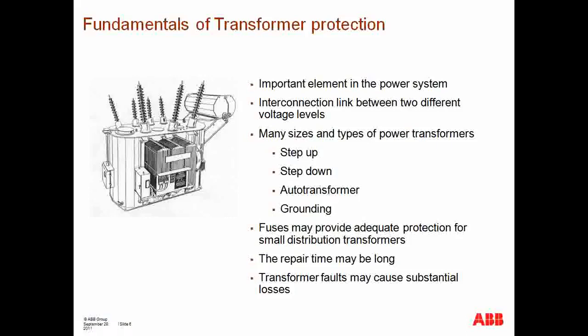And then under certain scenarios, a grounding transformer, or what's also commonly known as a zigzag transformer, could also be applied to provide a source of zero-sequence currents and grounding for a particular network. There are other types of transformers that are utilized. You also have power reactors that are utilized to provide reactive power injection onto the power system. You also have phase angle regulating transformers that aid in controlling power flow between 2 points within the network, and so on. But this is, again, as mentioned, a very important component of the power system.